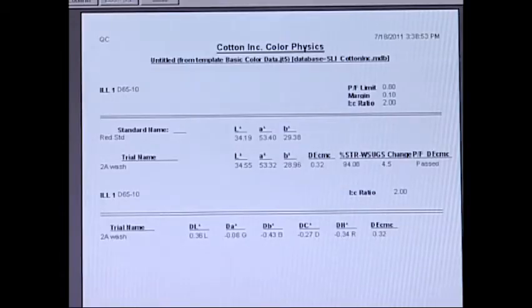Of importance is how the specimen differs in color from the standard. This difference is referred to as the relative strength. The values collected are used to calculate the relative difference between the two samples. The result of this comparison yields a numerical value which is termed percent strength. The final report of data gained through this procedure should include, as a minimum, the following information: the type of instrument, the color strength value calculation, the specimen presentation, temperature and percent relative humidity, and the number of readings in the measurement.